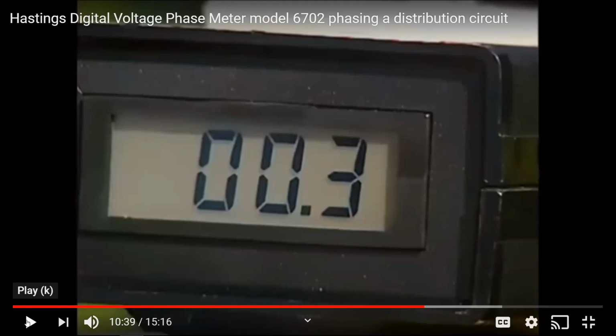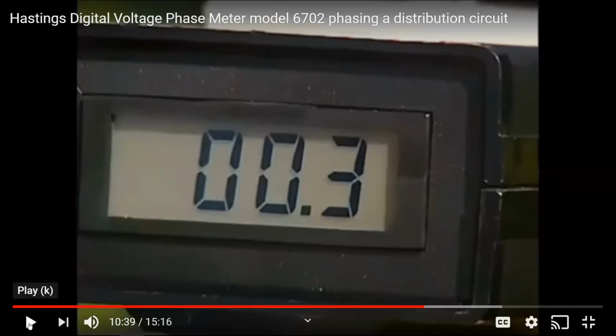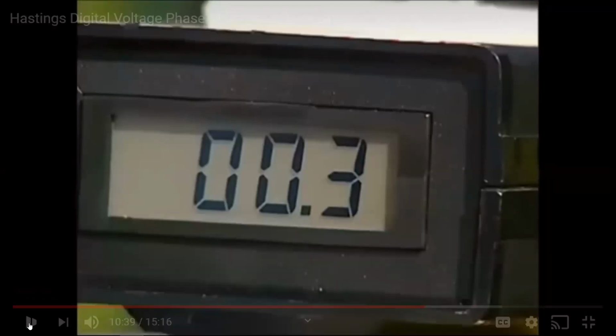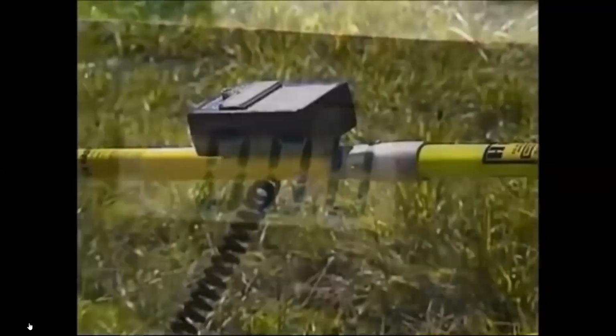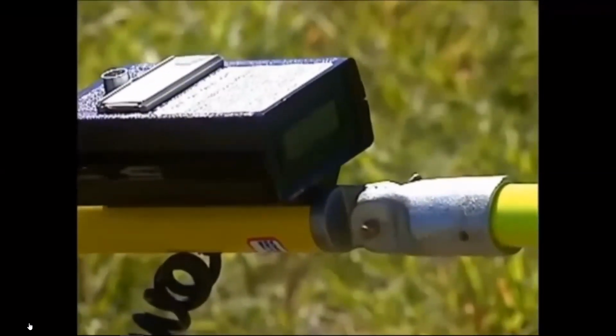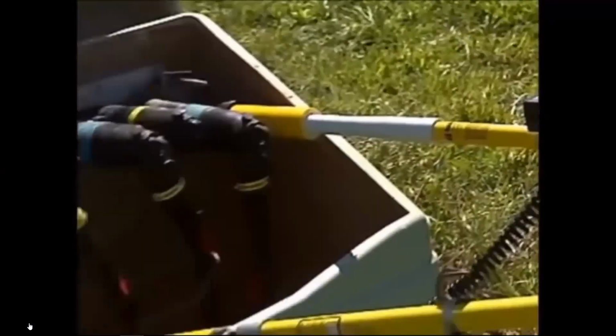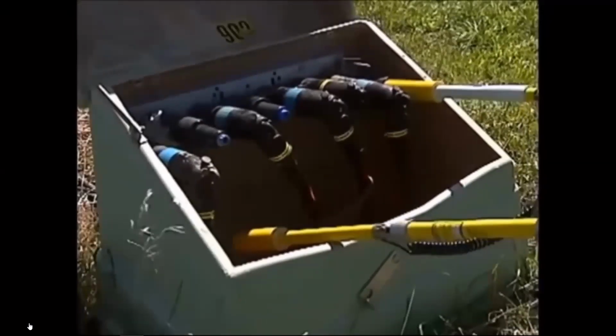How much voltage is on the cable? 300. 300 volts. That's how much of a charge that still remained on that cable before they grounded it. Ground your sticks every time after you high pot cable, and ground the cable. A short duration went to 0. John, it's very important that when we discharge the cable, the discharge time needs to be equally as long as the charging time. And even though the meter reads 0, it still may have a charge on it.